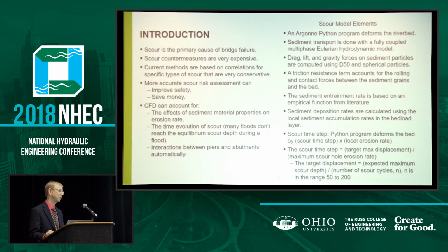We were using mesh morphing, some advanced mesh morphing techniques that are available in the 3D CFD software. And you've got millions of cells in your domain. And the mesh morphing varies the mesh with the shear stress in a user-defined function that is the rate of entrainment.